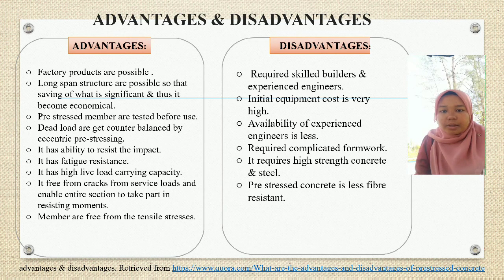Advantages and disadvantages of prestressed concrete. Advantages of prestressed concrete, there are nine. First, factory products are possible. Second, long span structures are possible, so that saving of weight is significant and thus it becomes economical. Third, prestressed members are tested before use. Fourth, the load gets counterbalanced by eccentric prestressing.